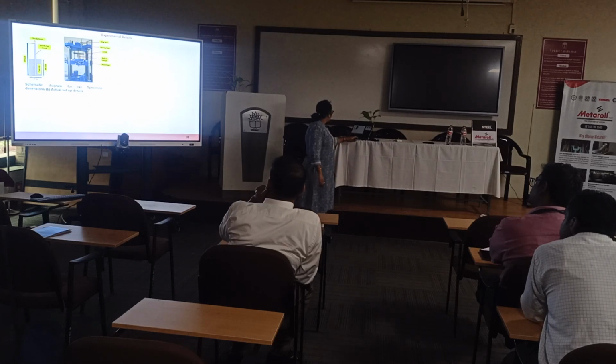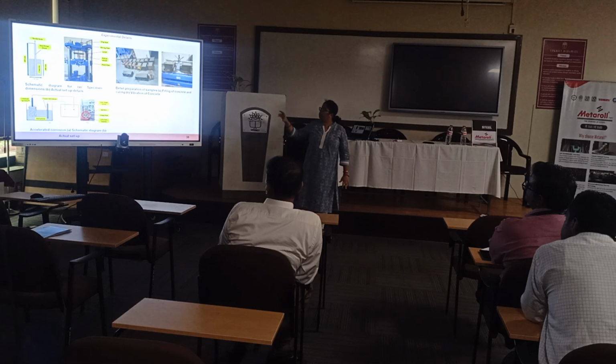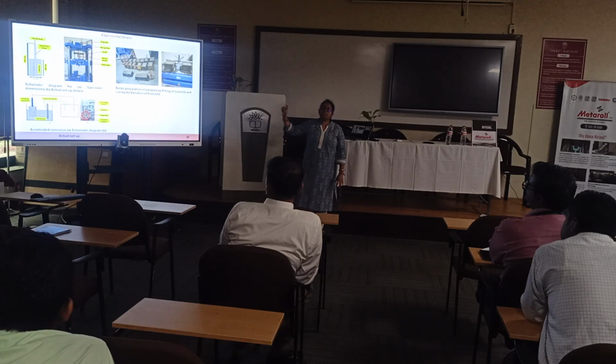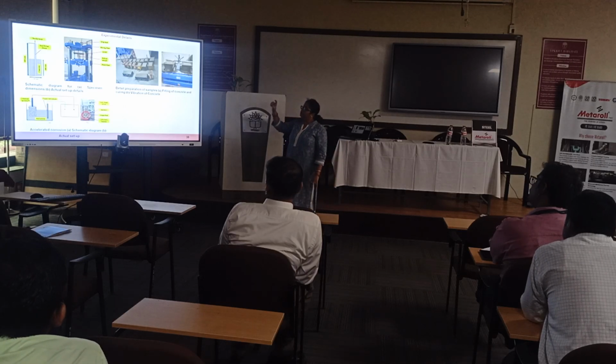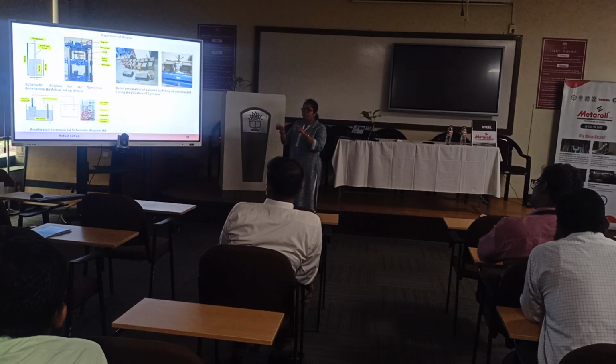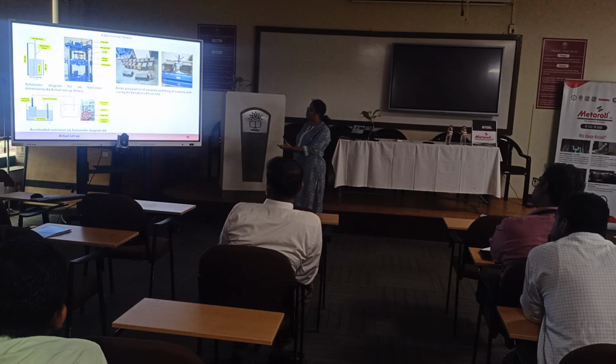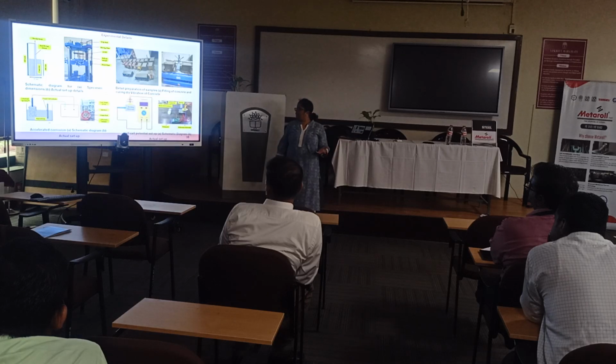Now, rather than going back to the other part, this is a very small part I just covered. Now, we do a parametric study. What parameters do we change? We change the cover to diameter, that is, the diameter of the concrete specimen, and the embedded length variations. We also do some variation with corrosion, accelerated corrosion, and we do more testing in terms of conventional as well as piezo sensor based methods.